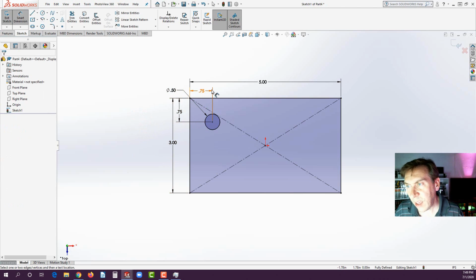All right. And so with that, now we want to mirror across. Now, you could put them all in individually, and I recommend that in the training guide. But I'm going to show you something a little bit more advanced today. This is something we're going to learn next week, but I'm going to show it to you in advance if you want to try it. Because this is going to speed things up a bit, so you don't have to redraw and dimension that in all 4 corners. Find the line tool and hit the little arrow to the right of the line tool and find center line.